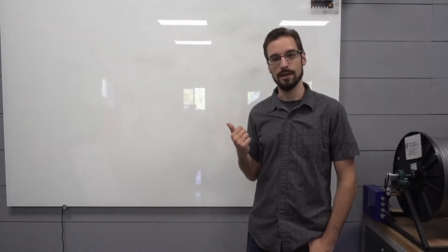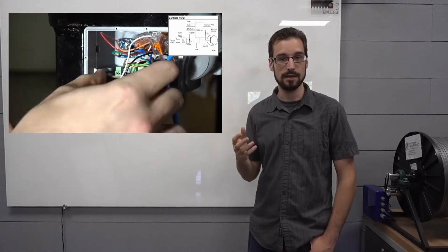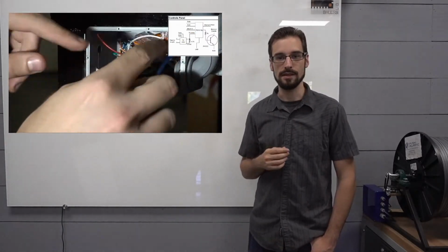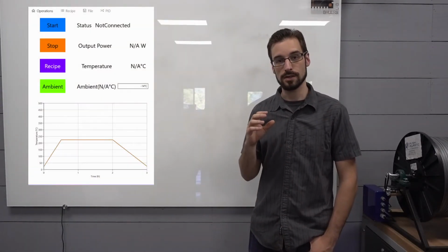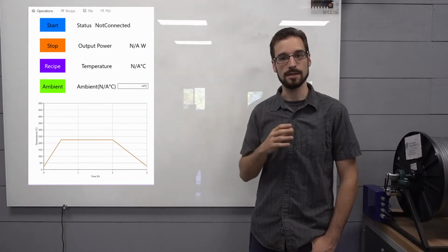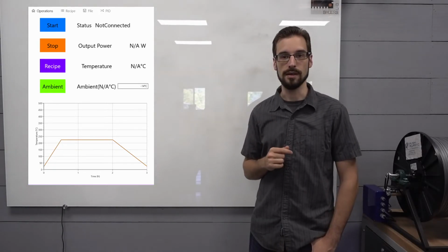So now let's move on to the microcontroller, and this is going to be the Cypress PSOC that we like to use. The HMI is going to be talking to this thing through a serial USB connection. It's just a nice, easy connection to set up. So the HMI just controls the system by sending the basic commands and the recipe set points, the array of recipe set points, to the microcontroller. Then beyond that, everything else in the control scheme is done by the PSOC microcontroller itself.